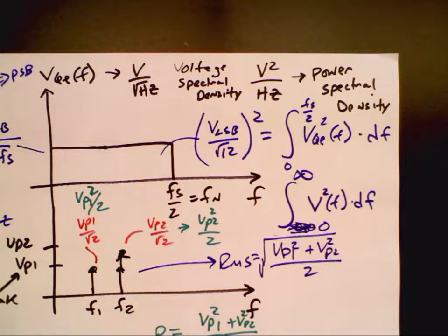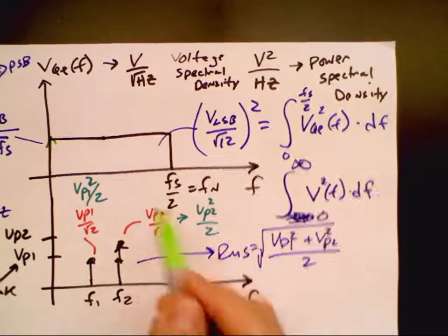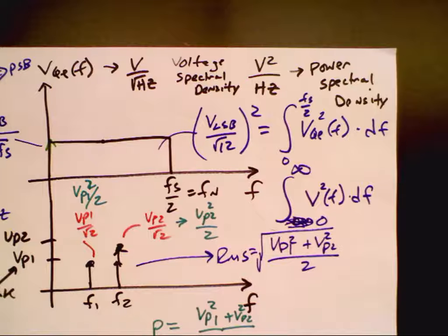So let me ask you a question just to make sure everybody's following. If I put a DC signal into the ADC and I ask you to sketch the spectrum of the quantization noise, not the level, just the spectrum. I'm assuming everybody knows that it can range between 1/2 LSB and minus 1/2 LSB. What is the spectrum of the quantization noise when I put in a DC level? Yeah, impulse at DC. It would just be right here. It doesn't look like what we just derived. There's nothing magical here. It's just a model we're going to use throughout the remainder of the class to model quantization noise. Any questions?